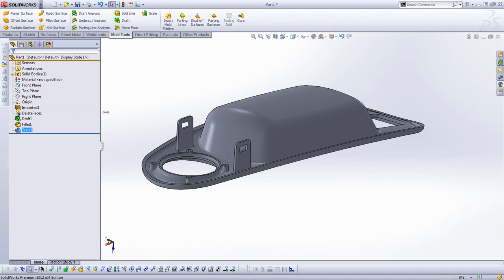Makes the part just a little bit bigger, and then a lot of times it is helpful just to backtrack it if we put the scale factor in. So we can say scale 2%. That way we can at a glance see what our scale factor is, so if there's ever a question about what the material shrink is, we don't have to go back in and edit the feature and potentially have a long rebuild time. We can see it at a glance.